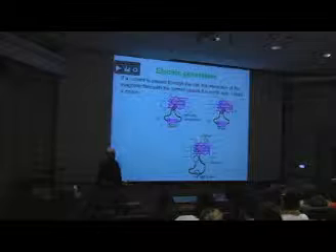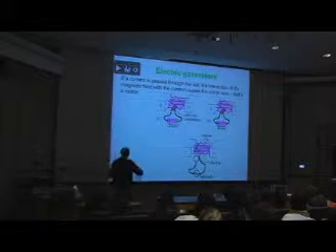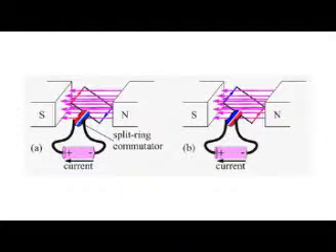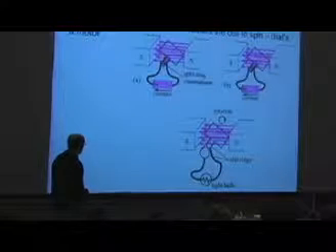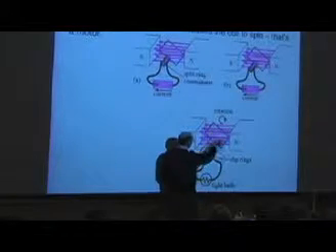And so basically at the heart of both things are just a loop and a magnetic field. In the top picture, we're putting electrical energy in that's being supplied by the battery and electricity running through that loop. Then we've got current in a magnetic field. We get forces that give rise to torques that make the loop spin. And we've got our split ring commutator that keeps the torque always going the same direction. Okay? So in picture B, the loop has actually gone through 180 degrees, but the torque is still going the same way. So you have to modify your connections to the loop a little bit when you use it as a generator, but it's really at the heart the same thing, same loop in the same magnetic field.